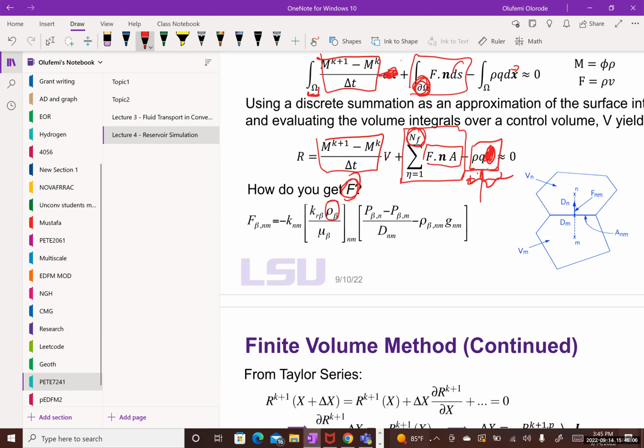When you get the delta X, which is delta P, which is single phase pressure, add that delta P to the pressure you had before. Then you've updated your P. Have you converged? If you haven't, we're going to do all of that today. If you haven't converged, then you go to the next Newton-Raphson iteration, but you are at the current time step.